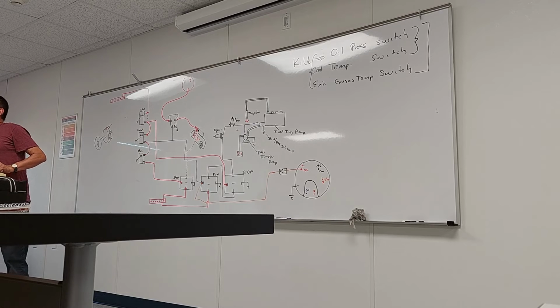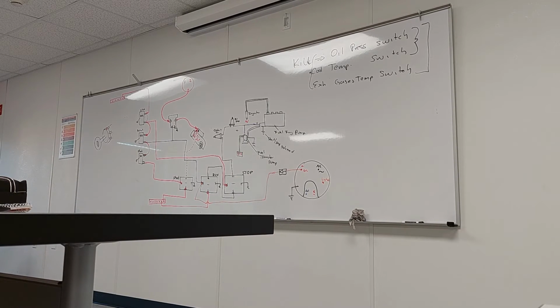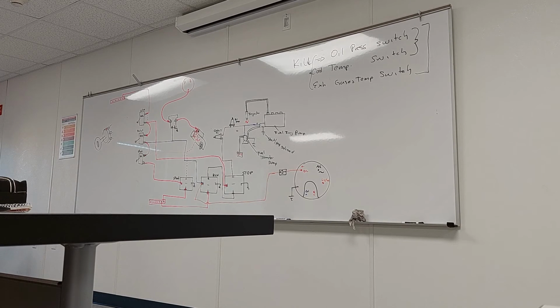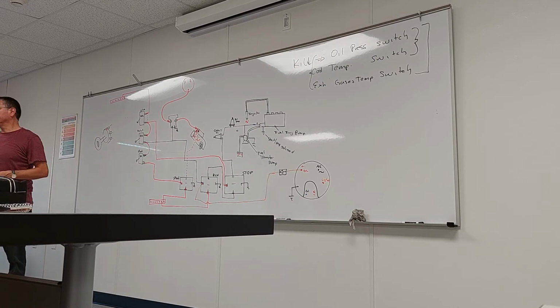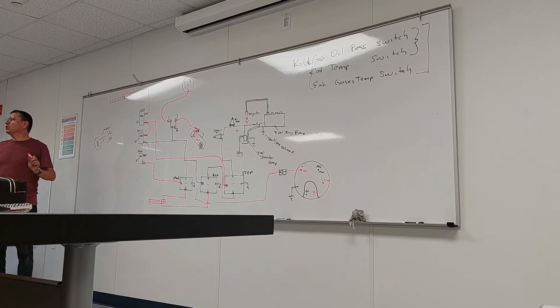The recommendation is to remove the air filter and plug it. Cover the air input and the engine stops immediately. Yeah? Remove the air filter and with a board or piece of wood, cover it and the engine stops immediately. It's quick, no? You interrupt the air or interrupt the fuel and the engine stops. In this particular case, we are going to stop it by interrupting the fuel. That's the most common.